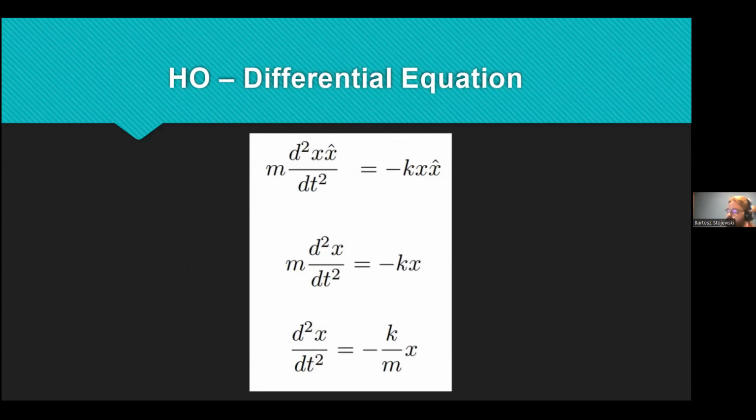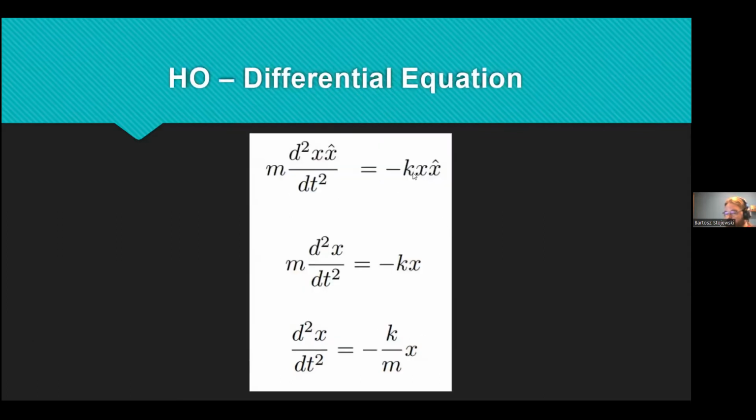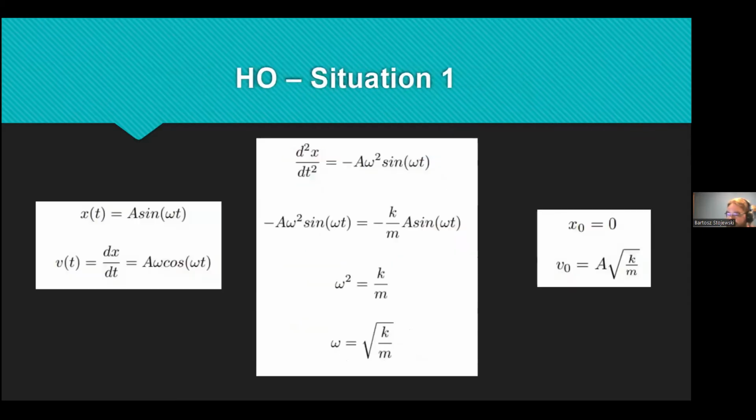By putting those two equations together, which is Newton's second law of motion and Hooke's law, we can get such a differential equation that gives us information what kind of x from t function we need to look for if we want to find solution to the simple harmonic oscillator. We could notice that without dampening, the motion is periodic and is repeated in sinusoidal fashion. This is why we can try to find analytical solutions with sinus.